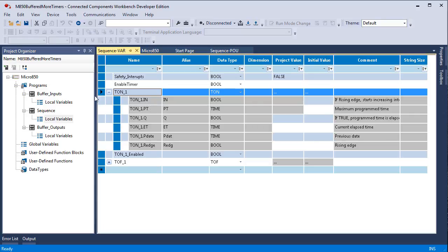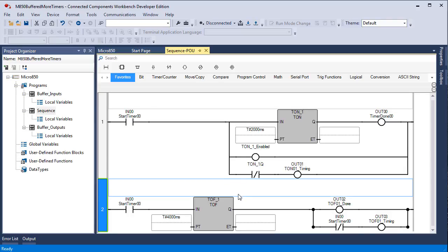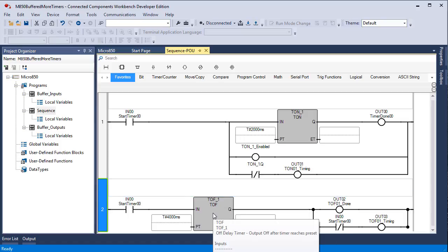The only reason that I included this other business in the lab is for RSLogix users if they're really stuck on the idea of an enabled bit. In both of these, we can create an enabled bit by simply branching around this instruction. Keeping in mind that the TOF is a little bit different because enabled means that it's queued up, but nothing's happening until it's not enabled.